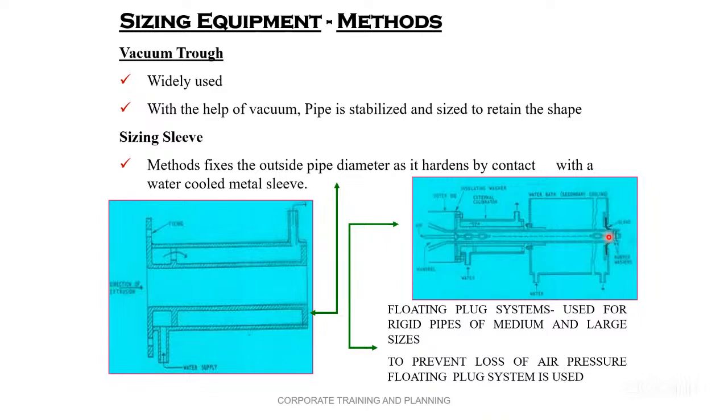It should not escape from the pipe. And therefore, we are adding a plug here. Due to the plug, the pipe dimension is maintained, and the pipe does not collapse at the exit also. And there are many benefits of the plug which is attached to the face of the die by a hook.